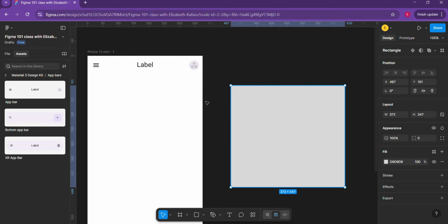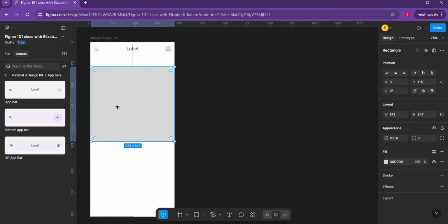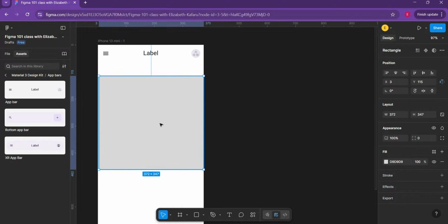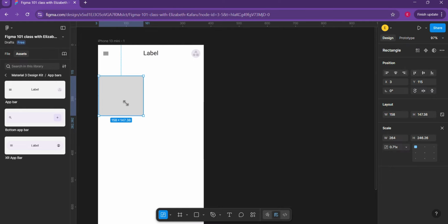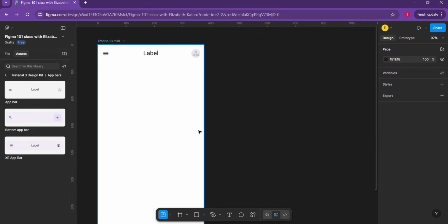I want to scale this. I want this thing to enter here. But let's leave it like this, and I want it to enter here. So I'll scale this. The shortcut is K. That's it. Just click K on your keyboard, then drag, drag, drag, drag, scale, make it bigger. Do you understand? So just drag. That's basically how to use scale.